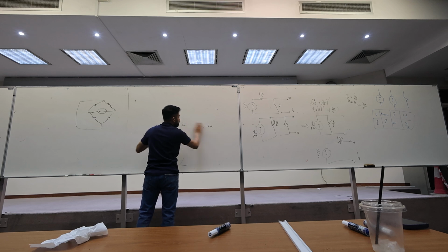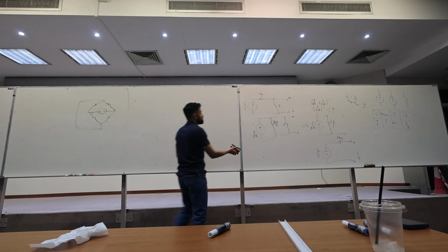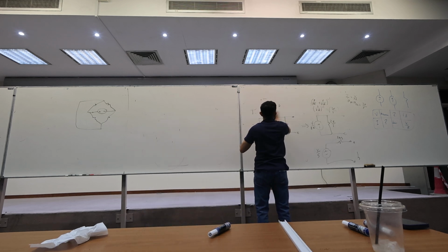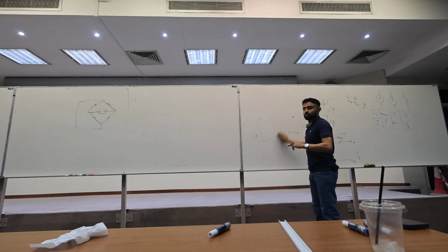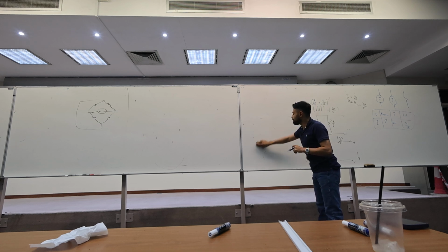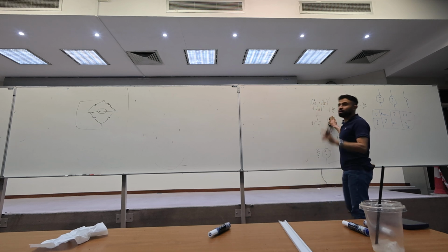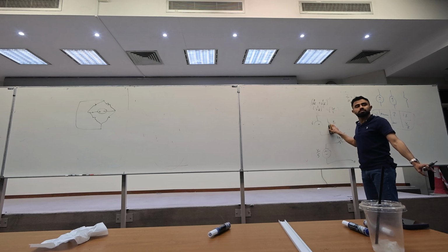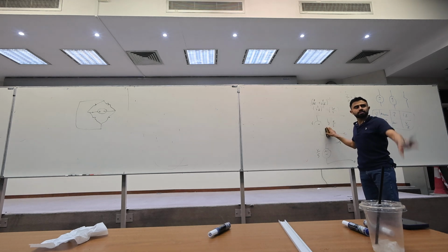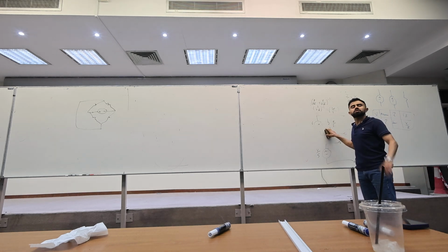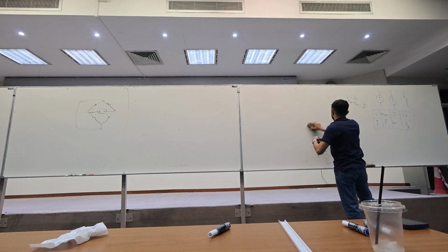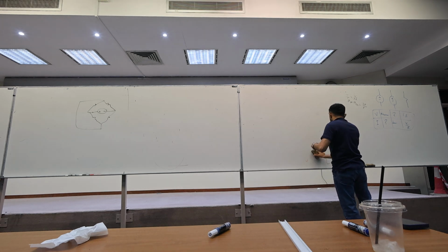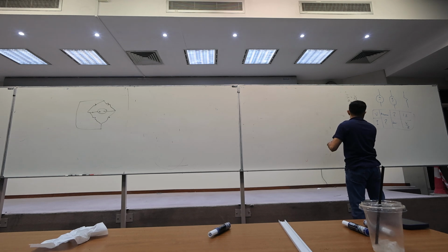And also there was an old exam question that one student asked me about. Maybe those two problems, when we solve them, will answer your question. Keep in mind, if two elements share two nodes, they are in parallel, regardless. Which is homework 1, figure 2: all three resistors on the right are in parallel, because they satisfy the parallel requirements.